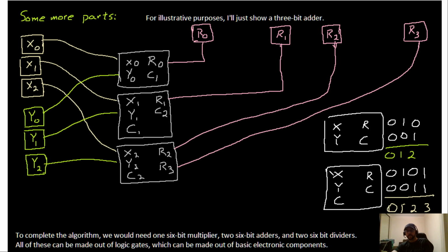So if we input all 3 of them are 0, then it's going to output a 0 for R and a 0 for C. If we input any one of these 3 as a 1, so we have a total of 1 coming in, I'll keep it with 1 instead of true, but coming on the inside we have one of the 3 is represented by a 1. It doesn't matter which, but any of them are represented by a 1. Then the output will be R is 1, C is 0.